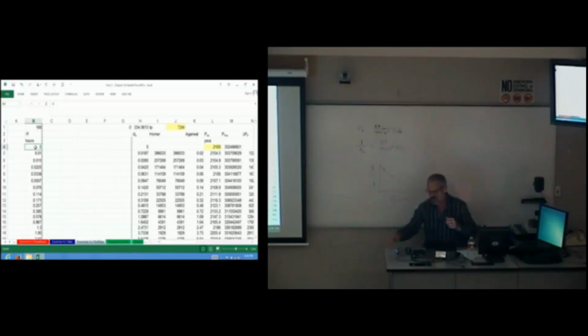Remember, I keep drawing this graph. On a buildup, we're drawing down, then building up. So this is your PWF. My first shut-in pressure is also my last flowing pressure, so my pseudo pressure corresponding to that is that number right there, 302. I want to make sure I'm using the right numbers. I just don't know.